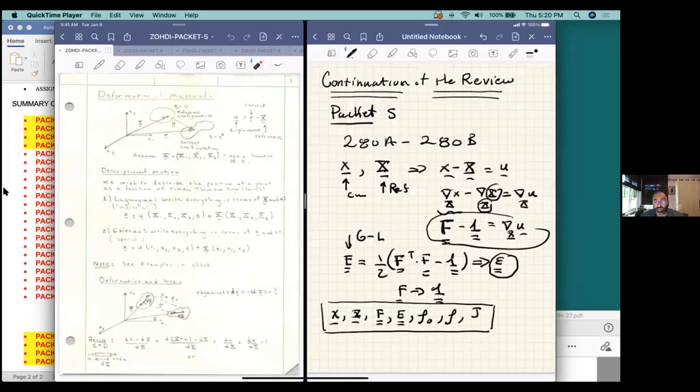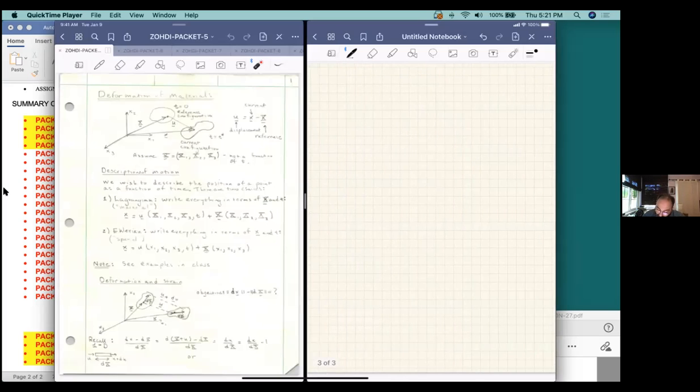And we had some classical examples with some relatively easy things to encode in project number 2, which gave you just basic deformation states of objects. Now, of course, there are many manufacturing systems that will produce different types of deformations. Some classical ones, of course, are things like extrusion, where we take an object that starts like this, we put it through some kind of a hole or orifice, you push it through, and then you start to produce long, thin wires.